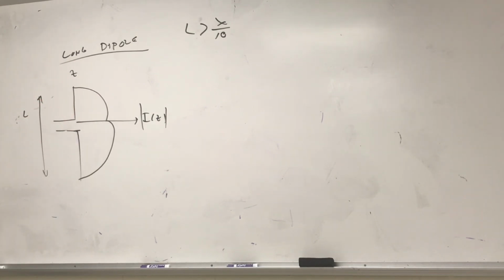But the point that you feed it has a lot to do with the impedance. And it's best to feed it symmetrically, right at the center. Same length above as below the point you're feeding it. And this is just a differential gap, as small as possible.